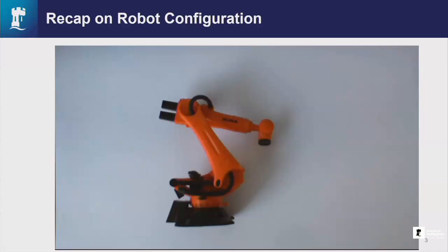So the base one allows the movement this way. Then you have one on what we would call the shoulder here that allows this link to move up and down around an axis of revolution coming out towards you. And then we have another joint, which we can consider the elbow, that allows that final link to move up and down. So that combination of the vertical rotation and the two horizontal ones allows the robot arm to position its end effector anywhere within its reach. Okay? All makes sense so far? Yeah?